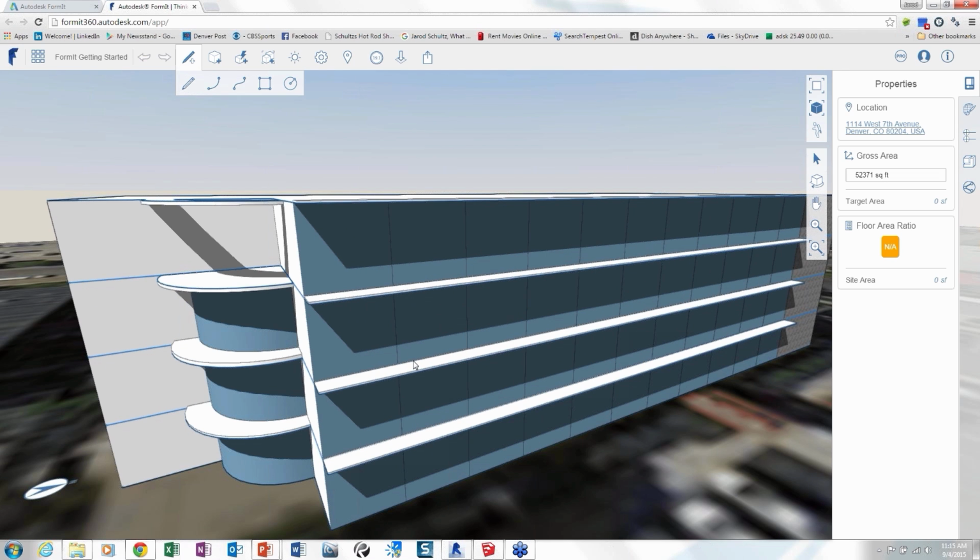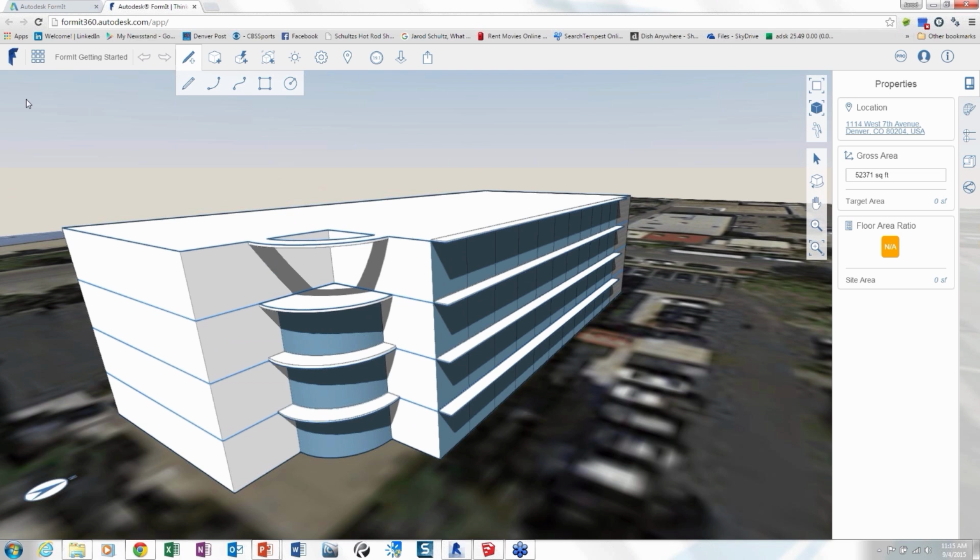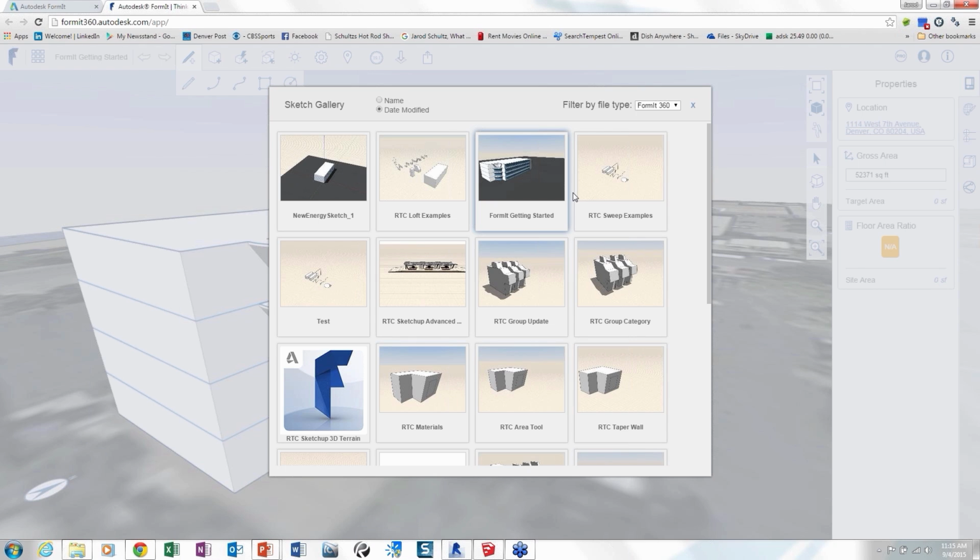Be similar to the concept or idea of what I did here to break up the surfaces. If I break those up as individual surfaces, I could have those as individual curtain systems because maybe they have different spacings to them. The curtain system tool is really good if you have a really regular repeating pattern. But if you wanted to do something unique, like an entry curtain wall or a special curtain wall on this facade versus that facade, you can. And if you want to get something more specific looking in FormIt, you could still do that and then create it easily in Revit. So anyway, a future webinar.